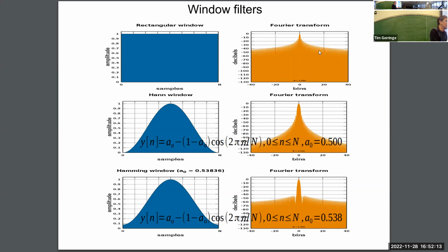So in the frequency response, you not only see that in general terms, as you increase the frequency, less and less of the input signal gets through to the output, but you also see oscillations of the frequency response with a frequency that corresponds to a period which is your averaging window, the n samples that you're looking at in your particular window.